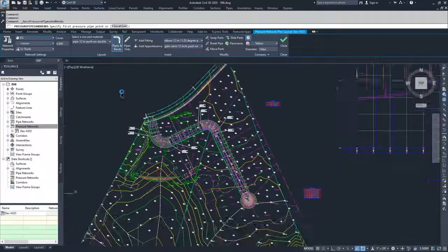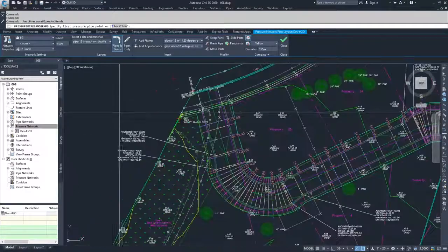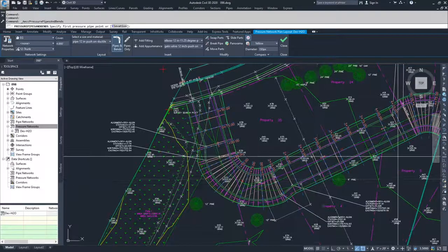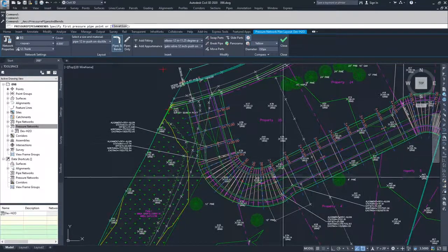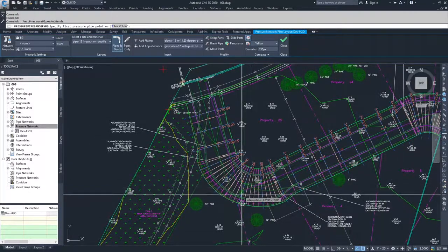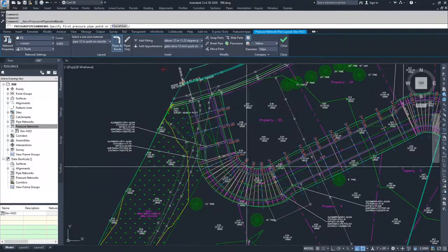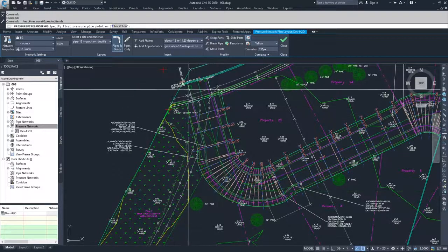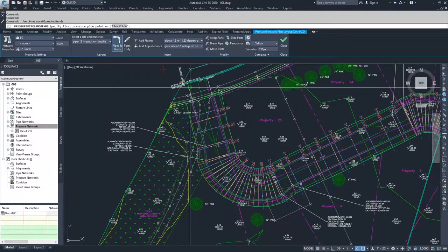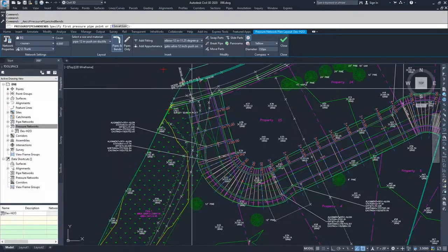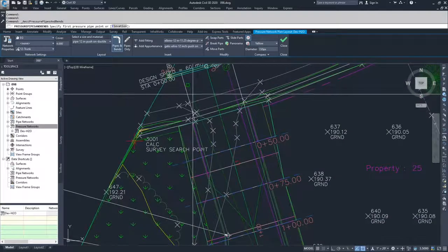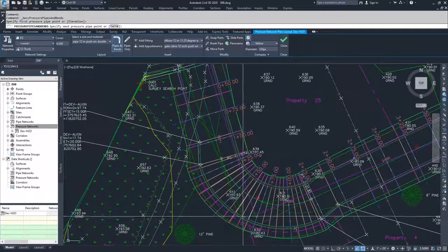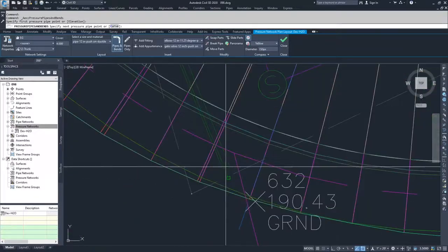What I did is I created a line that I knew would allow me to have a nice 90-degree bend around this corner. So I laid out a line along the sewer line here, and then I offset it down and out 10 feet, and then I projected it at a 90 up to here. So I'm going to use this green line that's right in here, and I'm going to snap to the end of it, and then come and follow along and snap to the end of it down here.